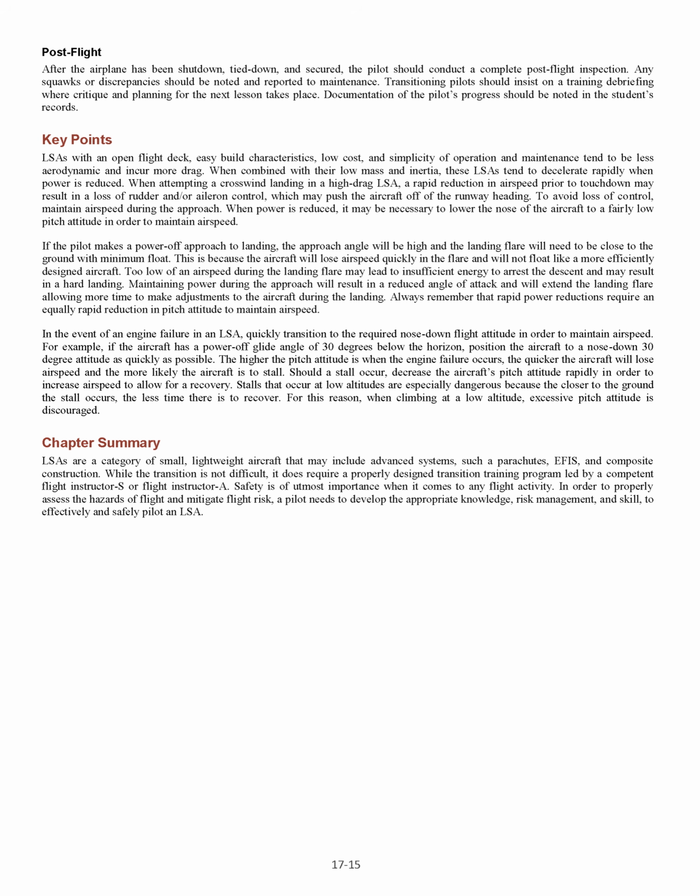When power is reduced, it may be necessary to lower the nose of the aircraft to a fairly low pitch attitude in order to maintain airspeed. If the pilot makes a power-off approach to landing, the approach angle will be high and the landing flare will need to be close to the ground with minimum float. This is because the aircraft will lose airspeed quickly in the flare and will not float like a more efficiently designed aircraft. Too low of an airspeed during the landing flare may lead to insufficient energy to arrest the descent and may result in a hard landing.